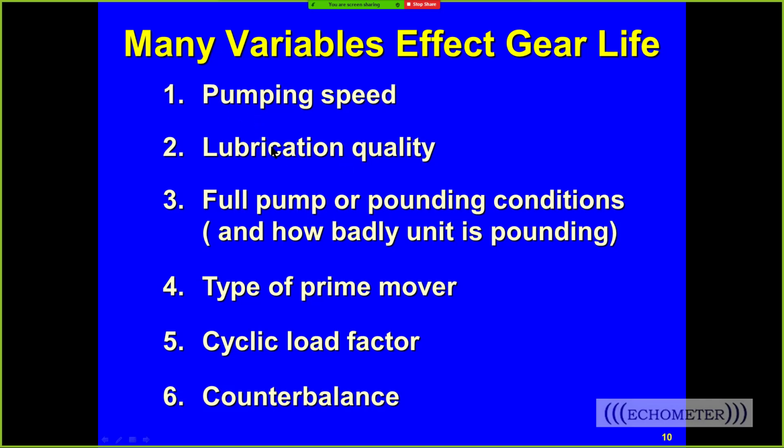Now, if you have condensation in your gearbox, that can cause damage to your gearbox. So lubrication quality is important. If you overload it, you'll get metal filings, and so periodically your gearbox should be tested. The lubrication should be tested, and if it has metal filings in it, it means you've overloaded the gearbox. If it has water in it, you need to replace it. If the gear lube is no longer quality, then you need to flush it out and replace it.